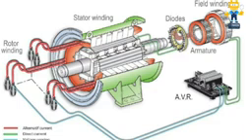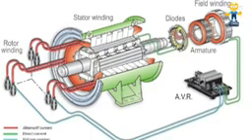In the self-excitation system, the main rotor, which is coupled with the alternator, revolves inside the main stator winding, and once the magnetic flux is produced on the main rotor, within the air gap the stator winding will cut the magnetic field. It will produce the electrical power.